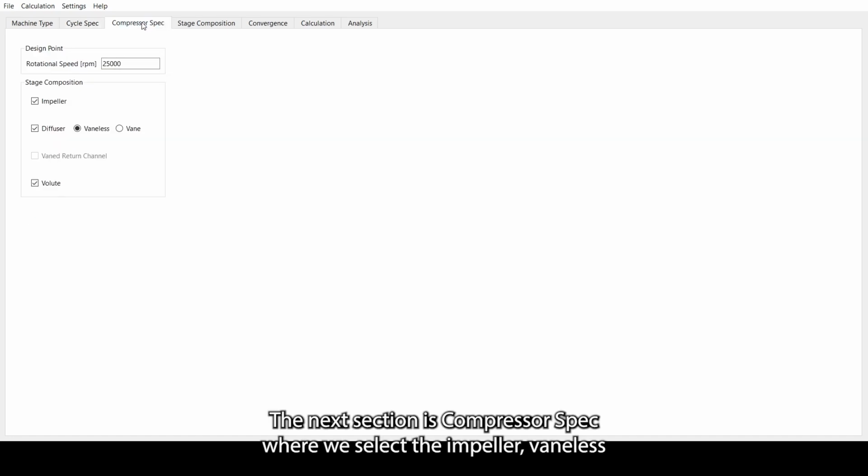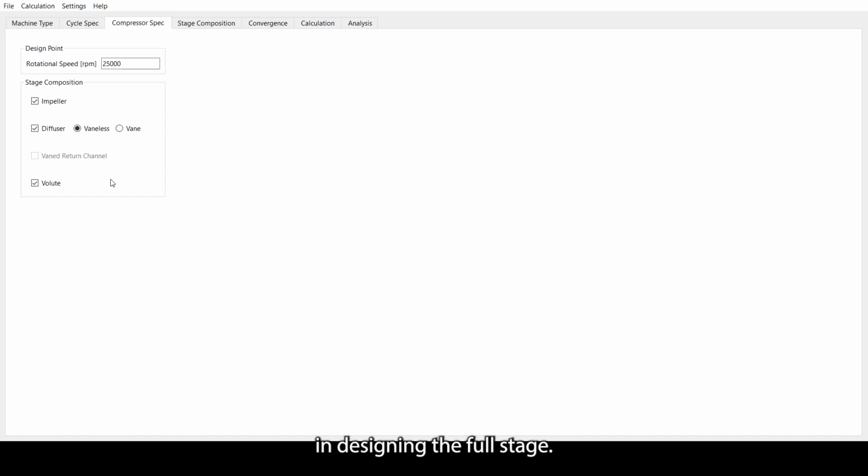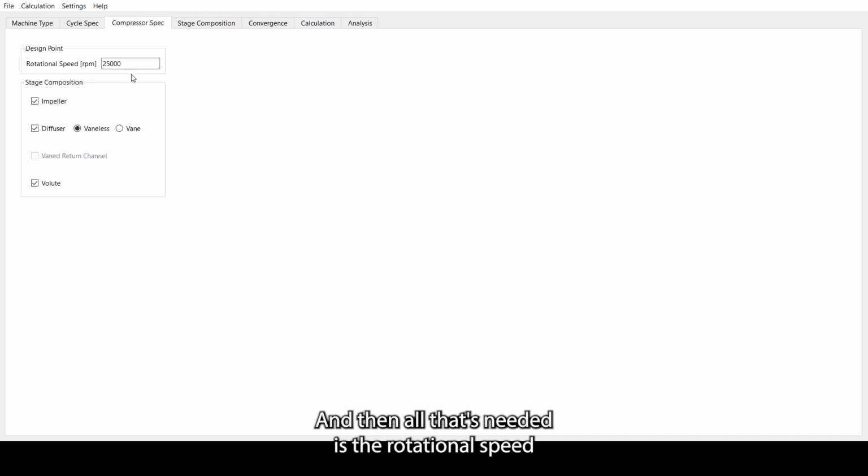The next section is compressor spec, where we select the impeller, the vaneless diffuser, and volute components, since we are interested in designing the full stage. And then all that's needed is the rotational speed, and the rest of the duty point, such as the flow rate and pressure ratio, is automatically taken from the cycle analysis.